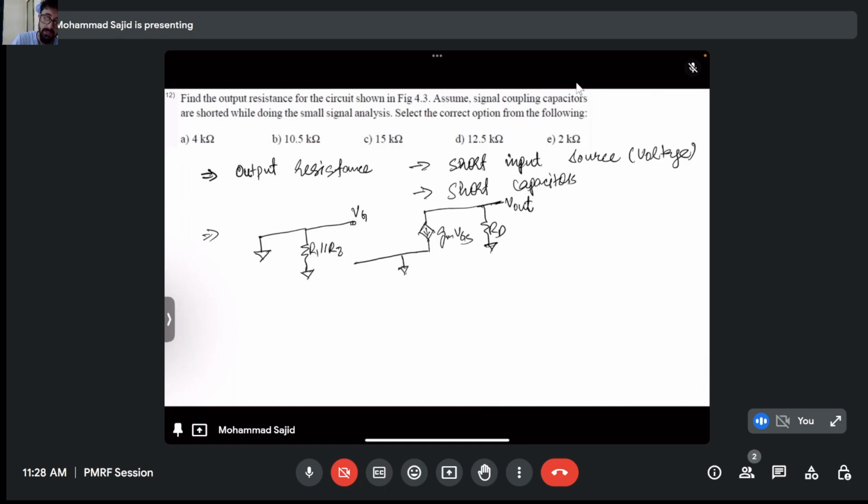So now what we will do is that we will connect Vx, Ix here. So let's see first. It is 0 volt here, so my Vg will be 0. This is also grounded, so my VGS is 0. So I can ignore this part easily.